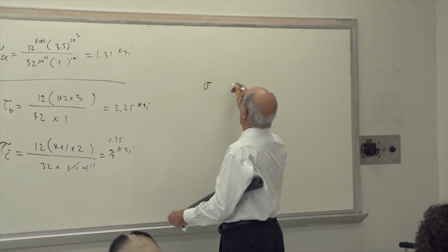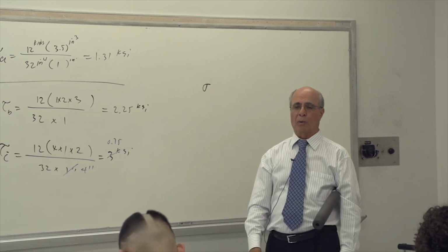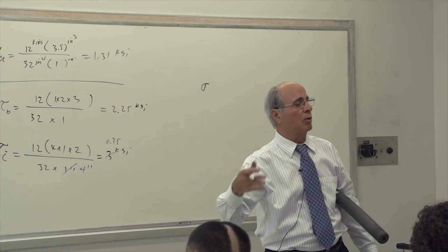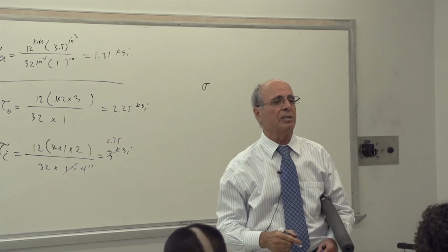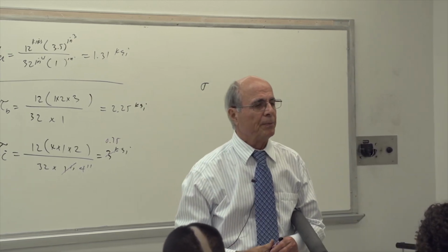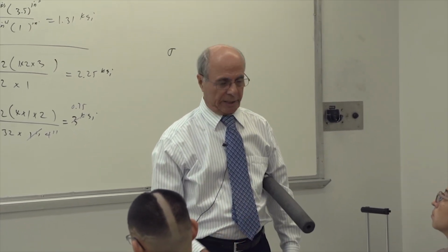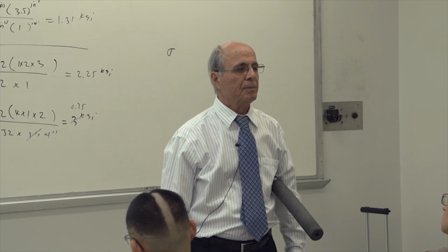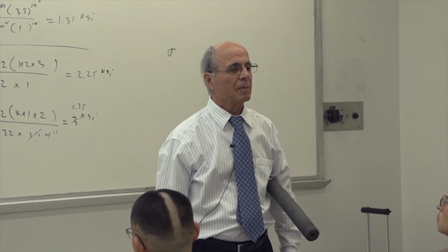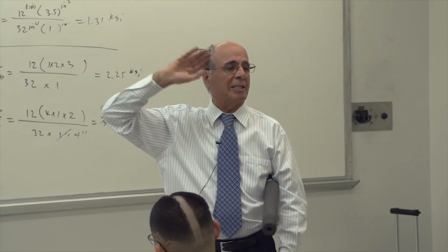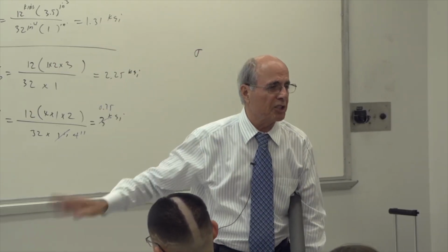The sign convention goes with the tension and compression. For the shear, this is the sign convention. I believe I have mentioned it four or five times on different occasions. Is that understood? So when we were asked to find tau max, it's going to be the 3 ksi. Correct. And then when we're doing the shear diagram is when we're going to need to know that shear force. The diagram is for shear force, and it has a different sign convention than shear stress.